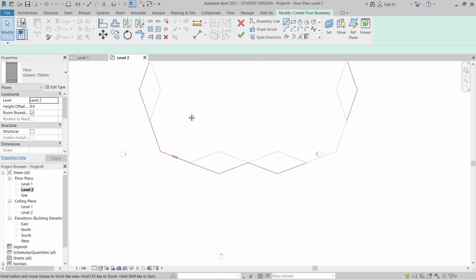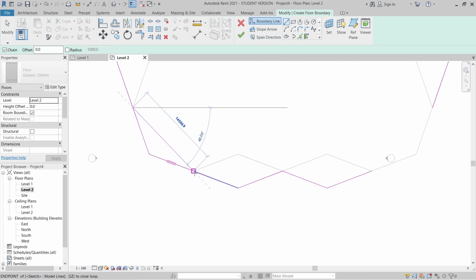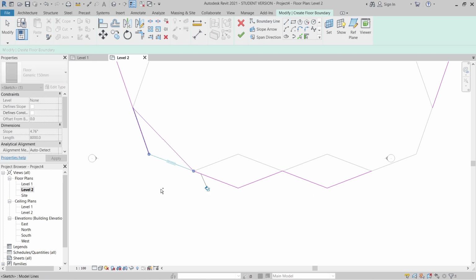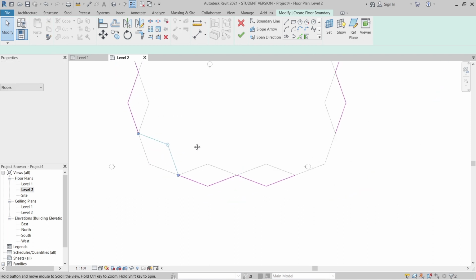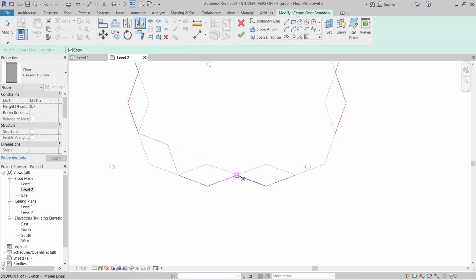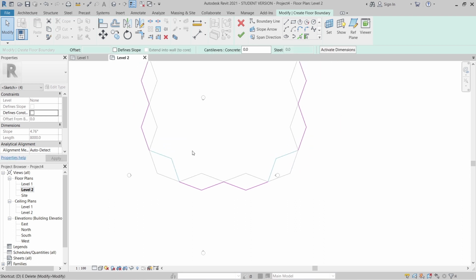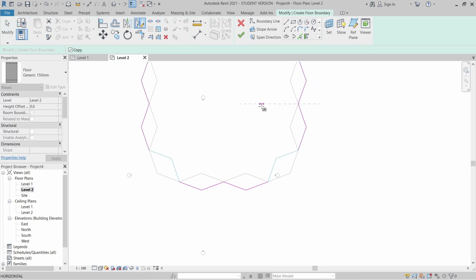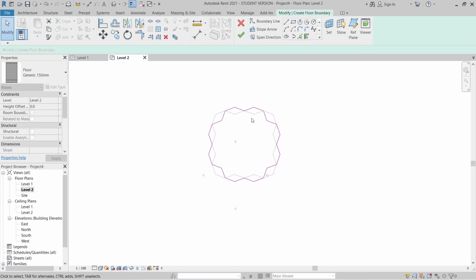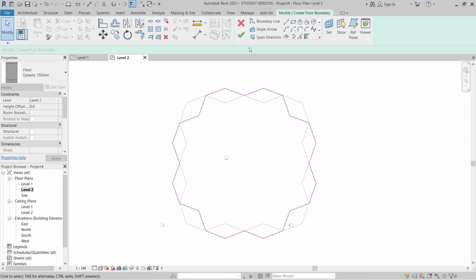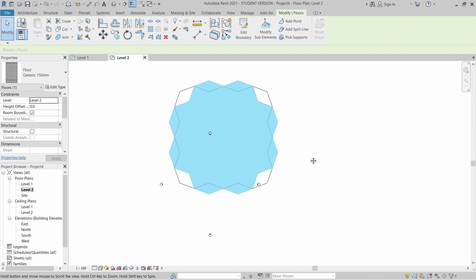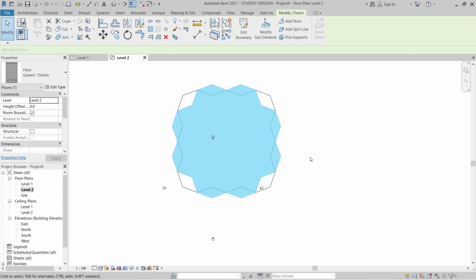Then use our line here for reference. Make it straight here. First, second, mirror 1, 2, 3. Hit delete or DE for shortcut keys, like my first two lines there. Then draw mirror here, and select this guy there. Then again for draw mirror, start here until here, then hit escape. Perfect, we got our second floor also. Just hit finish. Now it's time to draw our level, or we can straight away draw our curtain panel.